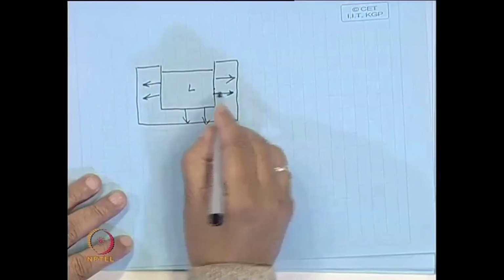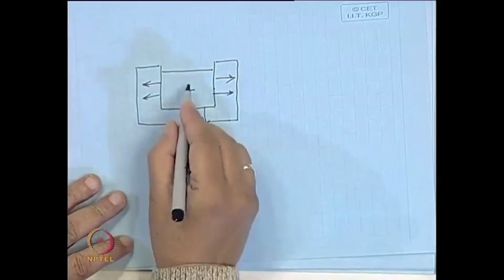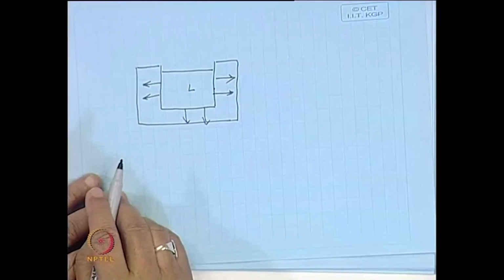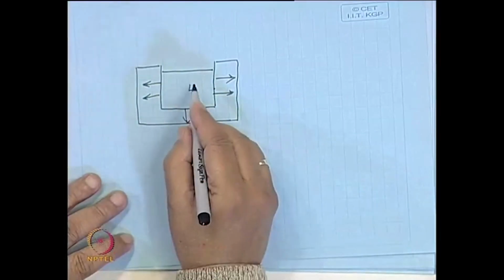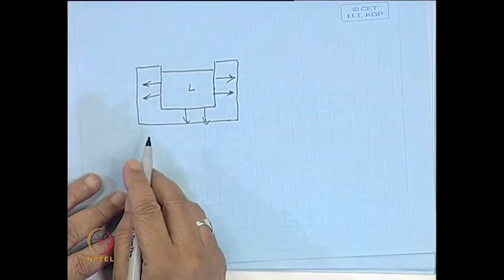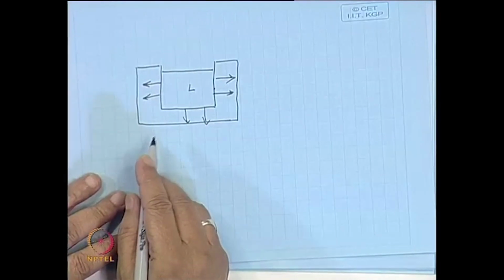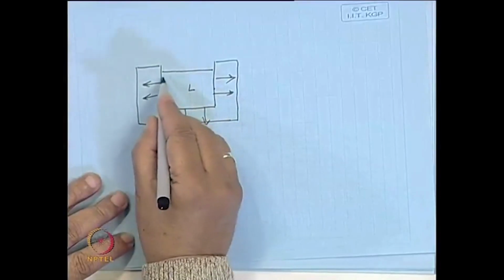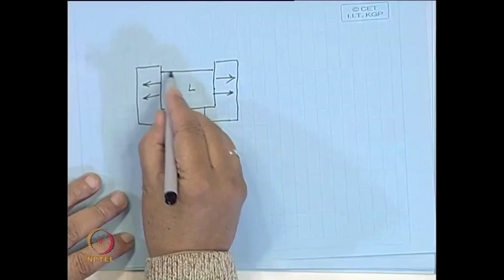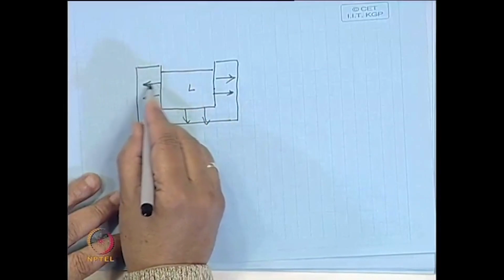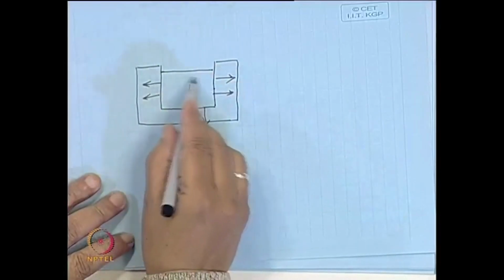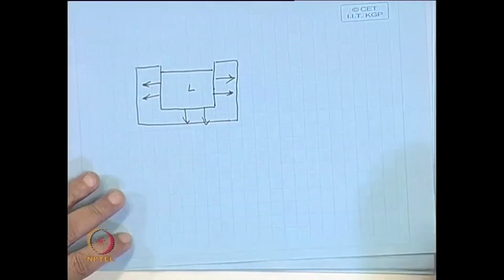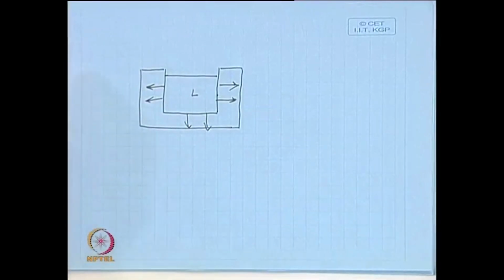The way that heat is extracted will determine how the structure will form, and we have also seen that for solidification to start, some amount of supercooling is necessary. So, the way the structure forms will depend on the way the heat is extracted from the liquid.